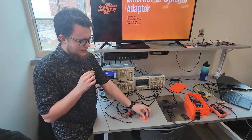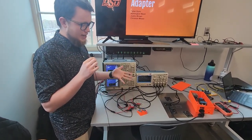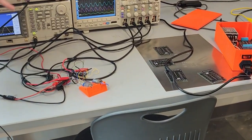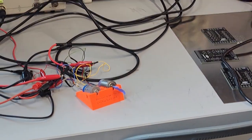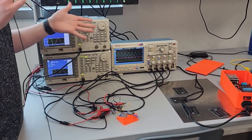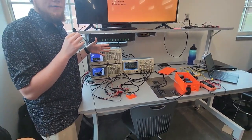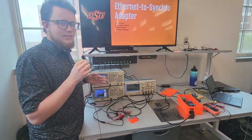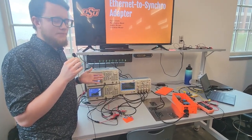Typically a dial will be placed on the transmitter side, and as you rotate the dial, it will rotate anything connected to it on the receiver side. As we change it, it'll rotate, and it actually acts kind of like a transformer. So it's 3-phase power, and then we need to vary the amplitude of all of the sine waves to pretty high voltages. It's about 11.6 VRMS, which ends up being about 32 volts.